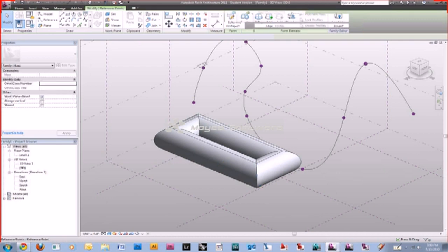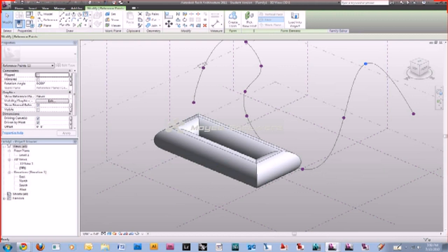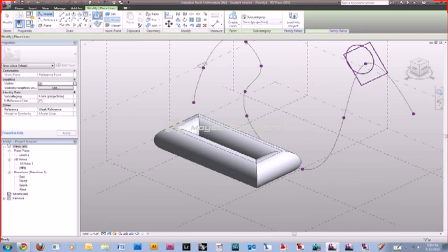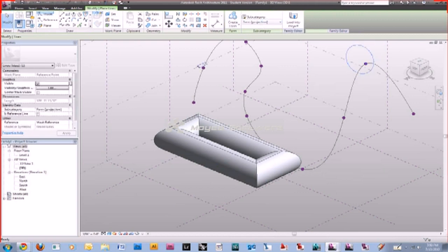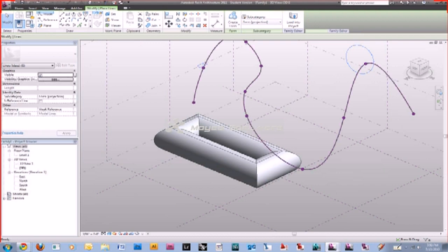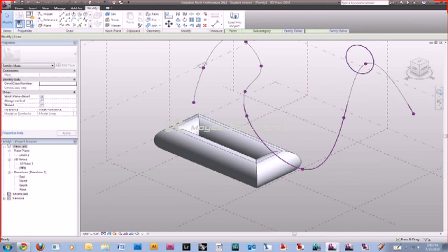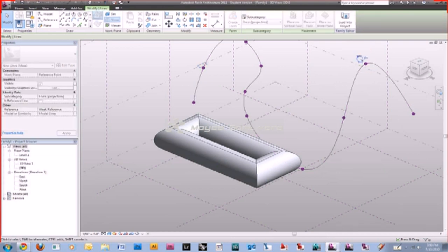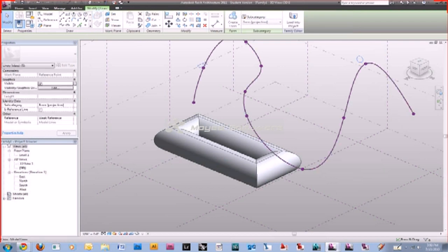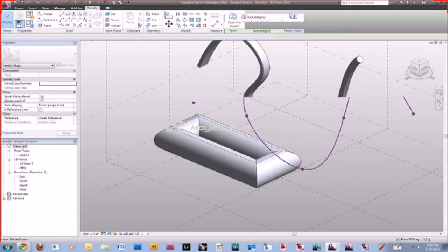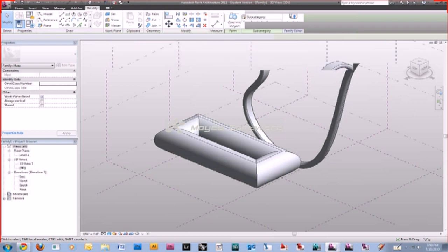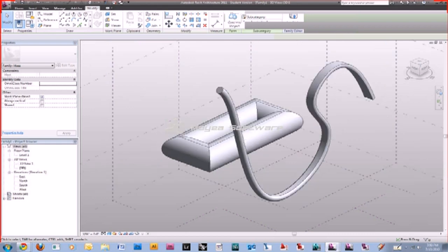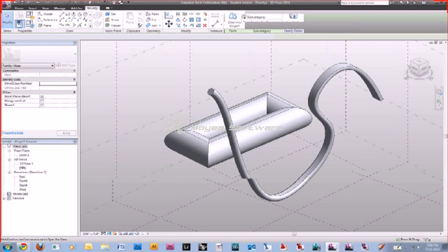So like I said, the first tools in mass editing are pushing and pulling. I think that's fairly simple. It's not really hard to understand. We already said to use the tab key to cycle through points or lines depending on where you're at. The next one would be the actual rotate command. We haven't gone over the rotate at all, but let's draw a square just to show the simple form of it.